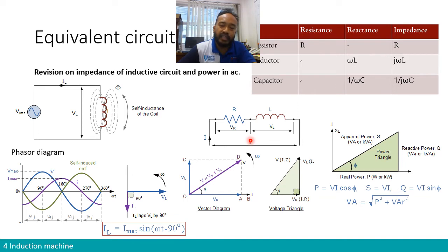the voltage supplied. Okay, so the lag is not 90 degree. 90 degree is only if the circuit is purely inductive. But if you have resistor, then it will be less than 90 degree. It has a certain angle of combination of both.